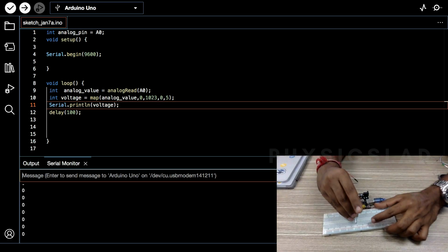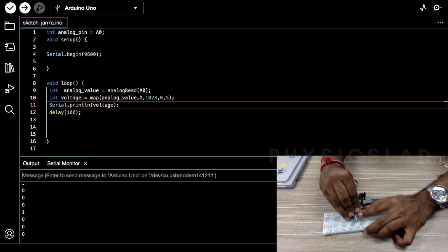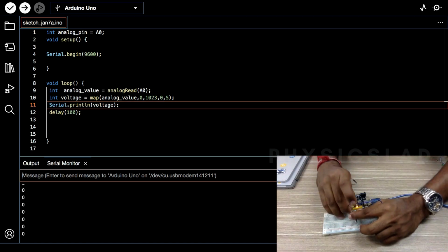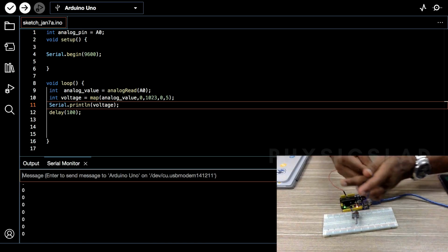So now we want to use the rheostat so we can see some actual input. We can give it some more predictable input. First, we'll connect our potentiometer to our breadboard. One of the pins, either left or right, will go to ground.